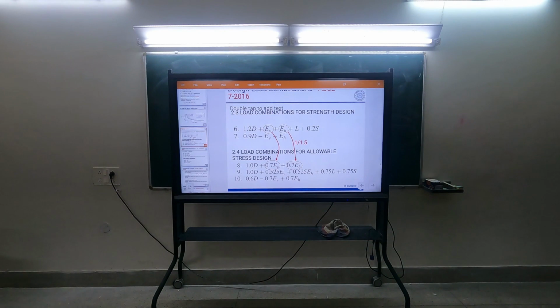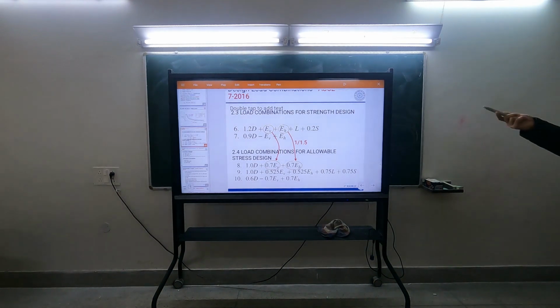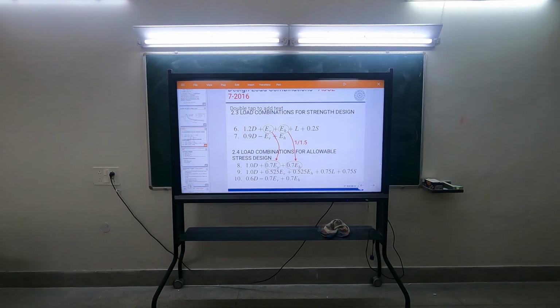And MCE is 2 times DBE. So how can it survive 2 times the earthquake, or 1.5 in American code, than what you are designing for? What is that factor? How did they come up with MCE? Why is MCE 2% in 50 years? Why not 1%? That factor is called overstrength.